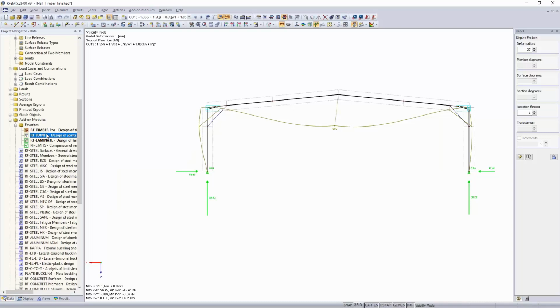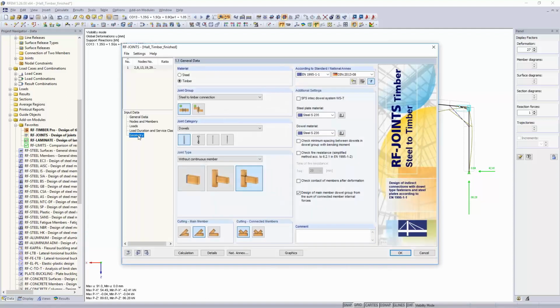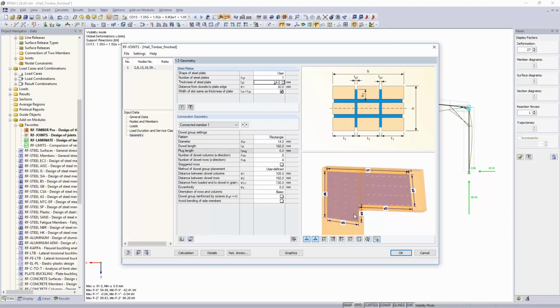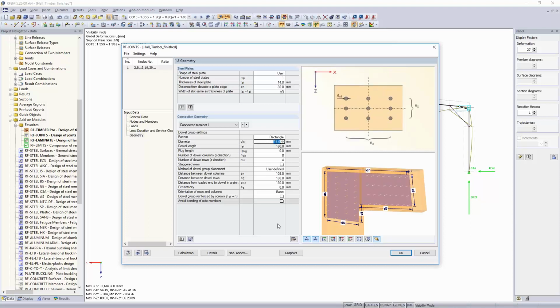So, with this information, we go back to the design tool. We saw that we had a pretty low loading of the steel plate. Now there will be a higher loading of the connection, because usually when you calculate with this slip in the connection, you have a lower loading of the timber, but a higher loading of the connections. That's what you really will find out. But the steel plate was only loaded 7%, so 2 plates probably make no sense in here. And therefore I changed that to 1 plate because I think it's still enough.